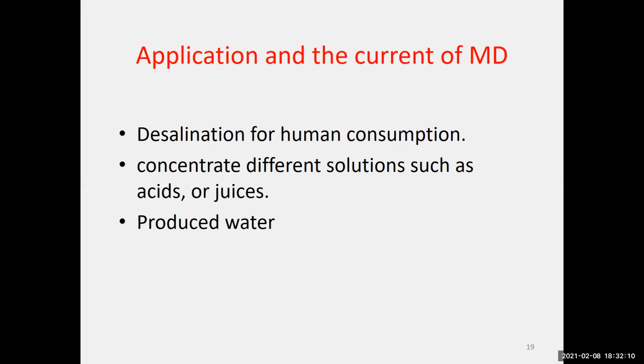Actually, it's only the HDH and the membrane distillation that are able to handle very high salinity, like the conditions in the frac water industry. You are talking about the oil industry, petroleum recovery. To recover more oil from under the ground, you inject water in. Water passes through the rocks and it collects some of the minerals. The water comes out with extremely high salinity, well above 100,000 ppm. So HDH and membrane distillation are technologies that are able to handle this high salinity.